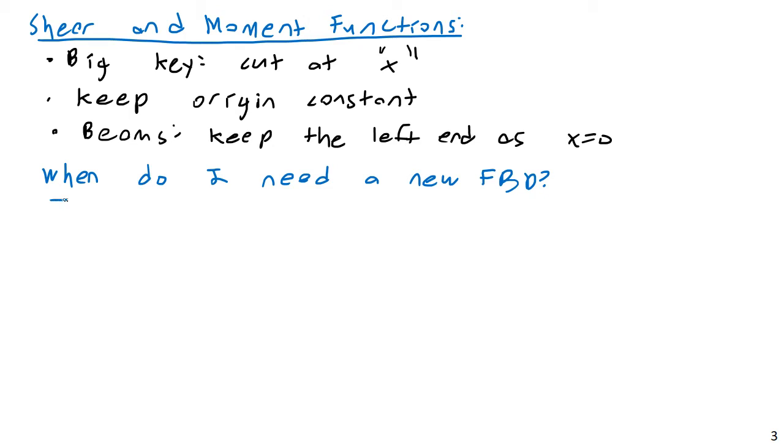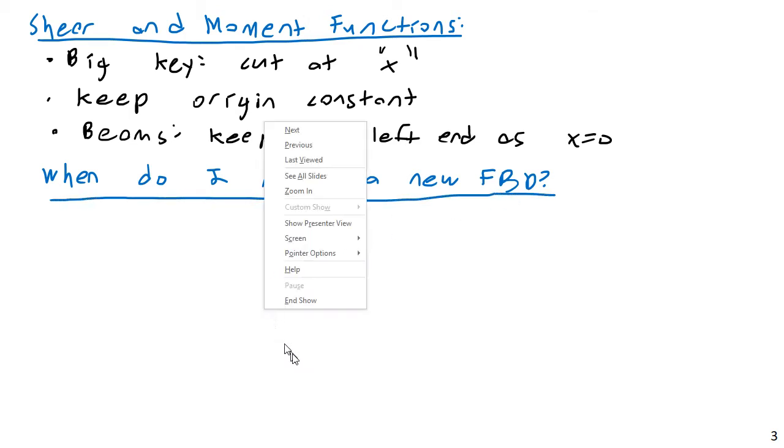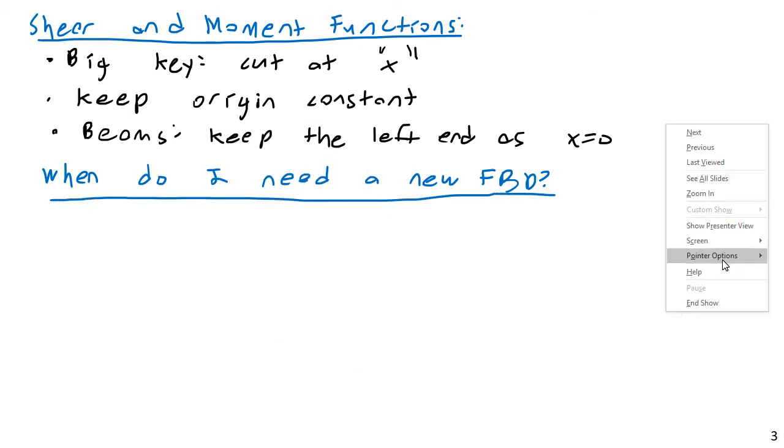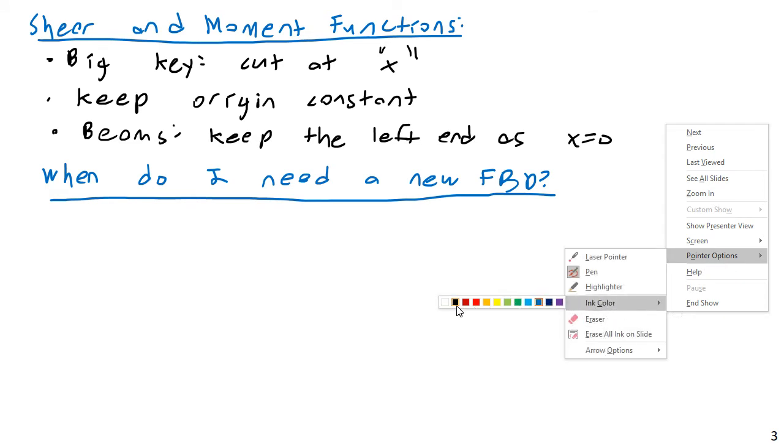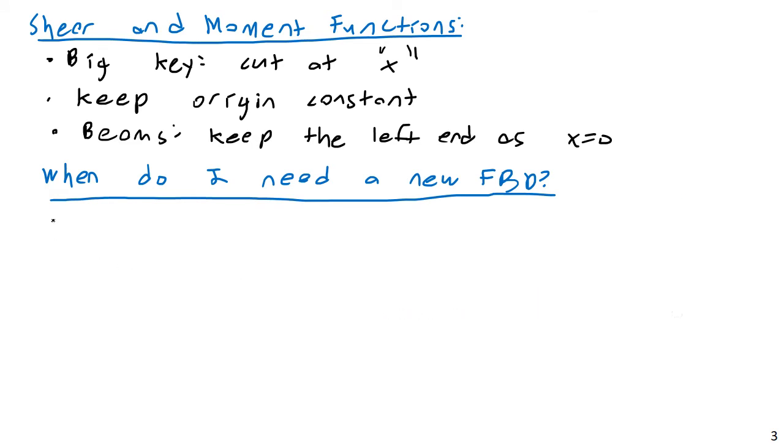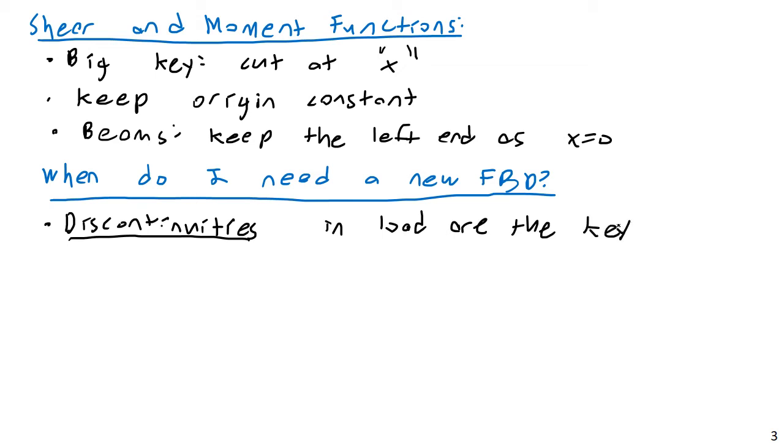When do I need a new free body diagram? Well, this is all based, we'll see later, on the fact that one of the methods of getting these is integration, and that should be a key. Discontinuities in load are the key. So, anywhere you have a discontinuity, those will form the boundaries between your zones of analysis.